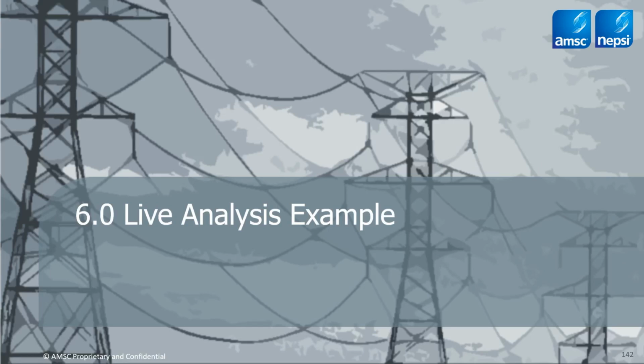How are transient harmonics analyzed and addressed? Again, for energizations, you would have to use a transient analysis program like EMTP or PSCAD or something similar, or even maybe put together your own transient simulation in Excel, which is fun to do. It's a possibility. You get a lot of rows out of it to simulate that much detail. But yes, you'd have to use a transient simulation tool for that.